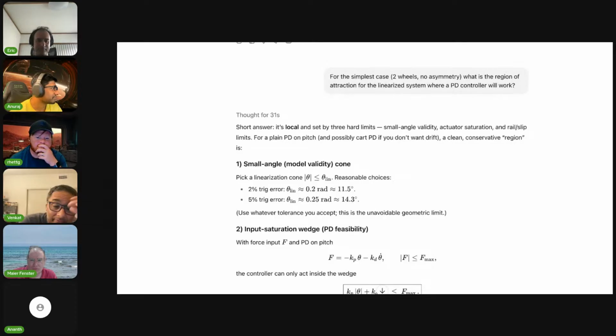So far, we've made the assumption that we are linearizing the controller and working near the vertical. And usually when you do that kind of linearization, you do something called estimating the region of attraction. There are systematic ways to do this using the eigenvalues. Usually the intuition is for an inverted pendulum, it's no more than a few degrees. At that point, PID type controllers will fail. And you can see that with the tumbler, right? If it falls over on the non-tail side, it can't pick itself up again. On the other side, if it's stopped by the tail, you'll notice it does a jerky motion to get back on. I suspect it does something nonlinear in the initial getting up portion. I haven't yet looked at the code.